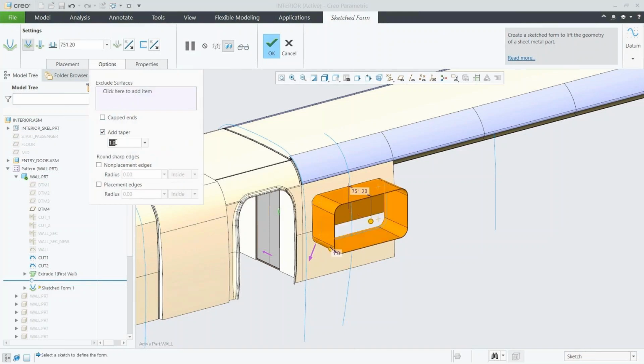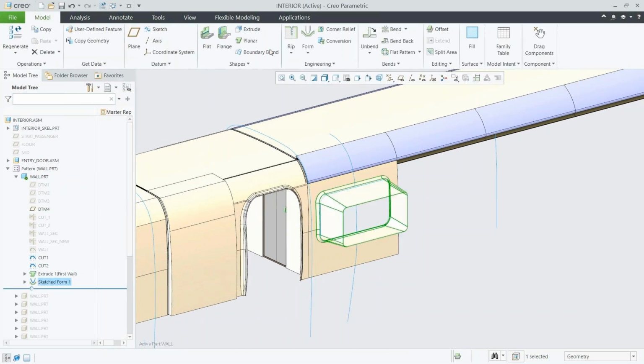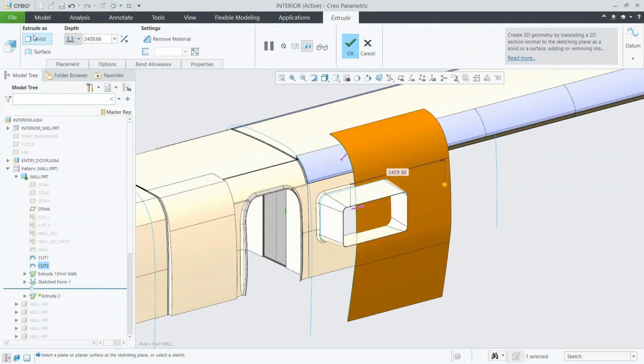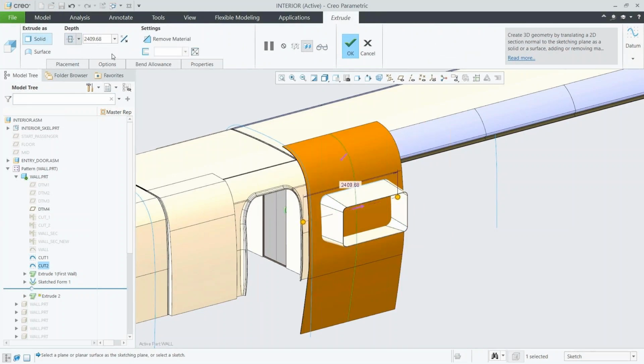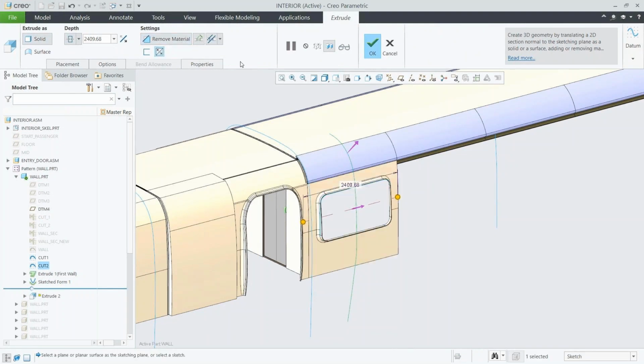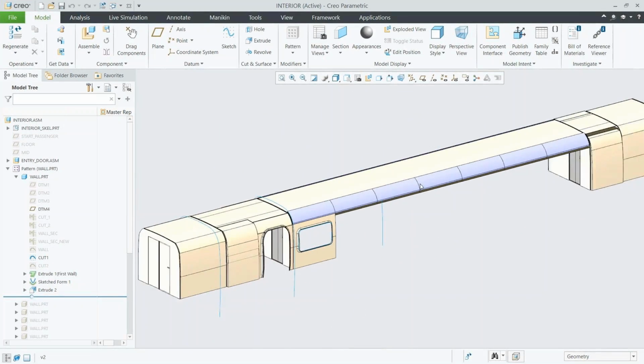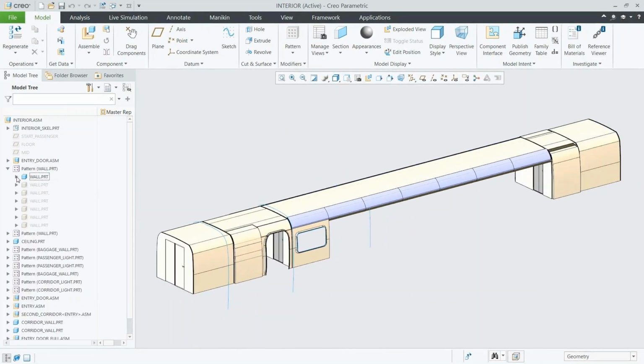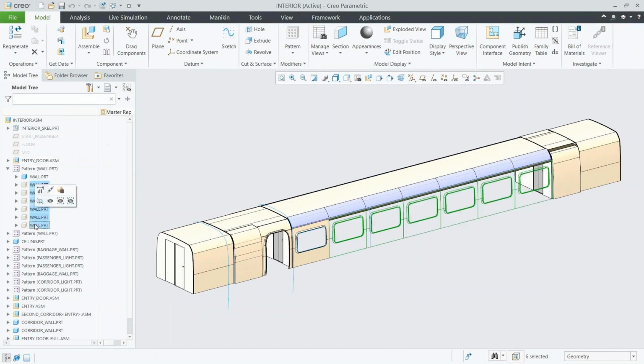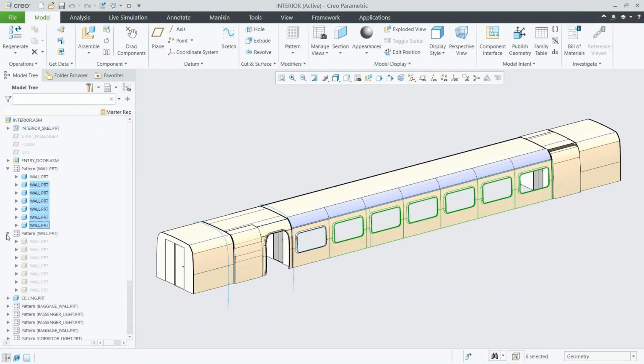and then like I said, this is just your typical work. It's just that you're starting with a sketch that was agreed upon at the top level that is referenced by everybody and can be changed very easily. So this outer wall is going to be the end of the window, right? So that's the end of it. If it's going to meet up with the exterior wall, the interior and the exterior wall, that's where it should be cut off. And so now that's referenced as well. Again, we can pattern that, make all of those the same so that if one is changed, others are changed as well. Keep the model flexible.